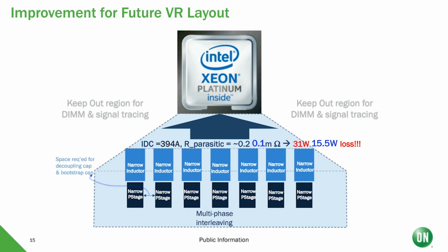Yeah, I think so. Another question that we have here: can you operate the power stages at their rated peak current indefinitely? The way we rate our power stages in terms of peak current is that we keep the ambient temperature at whatever it takes to operate at that current level, so that the junction temperature does not become destructive. So it really depends on the ambient environment.